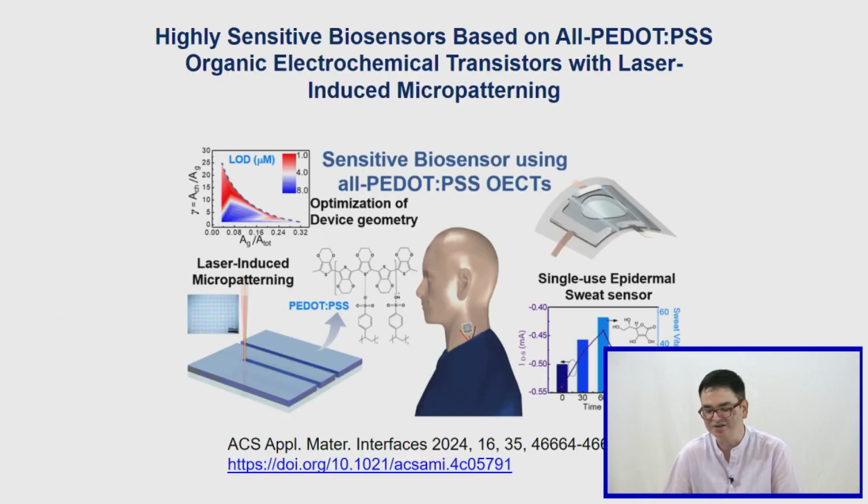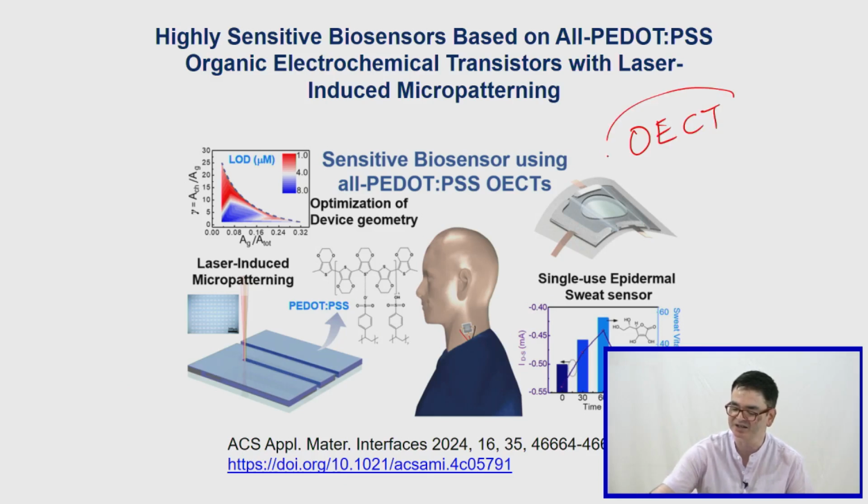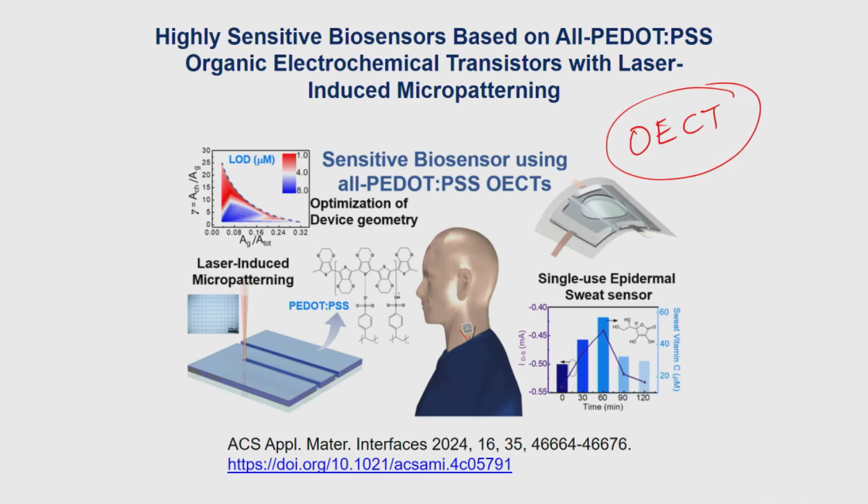Okay, let's start looking at some of the examples here, and then we'll have 4 specific examples, but let's have a look at this one here, which is what we call an OECT, which is an organic electrochemical transistor device. Yesterday the transistor device was explained by Professor Khaled. He mentioned having a gate, a source and a drain, right? And the gate part is the part where your solution, normally you have an extended gate, that's where your solution normally sits, and then you have a source and a drain, and you normally apply the potential, or you either monitor changes in the potential, or you keep the conducting channel, the conducting current, the conductance fixed, and you measure the changes in the potential there.